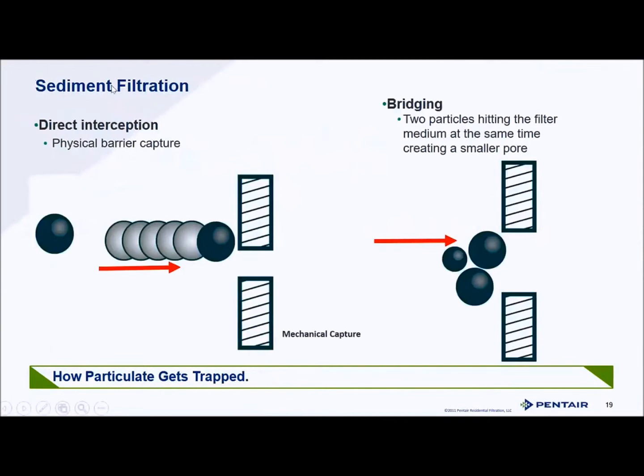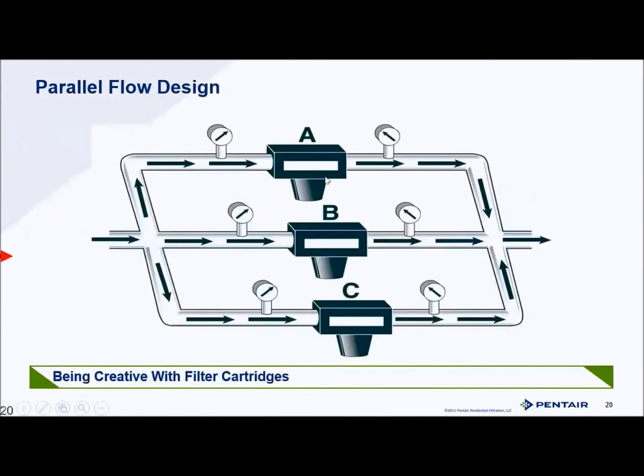So, how sediment filtration works in any filter: you're going to have basically a pore size. You're going to have that particle directly hit the material, or you're going to get multiple particles plugging up the pore size and capturing debris. That's how particles get trapped, either direct interception or bridging. Now, when it comes to drop-in filtration,